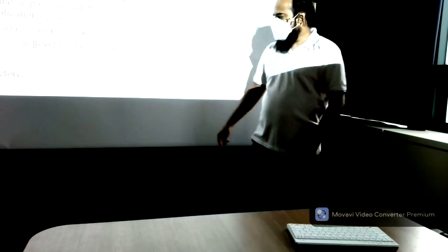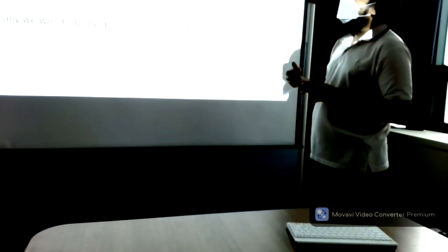So our guidance error should be less than or equal to the sum of the navigation error and the guidance error. Okay. So equation number 1 implies that we can guarantee a bound on the true guidance error. In other words, a small navigation error and a small estimated guidance error imply a good guidance.